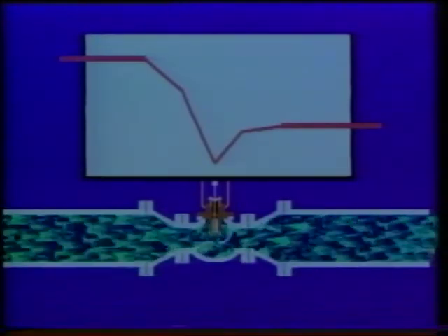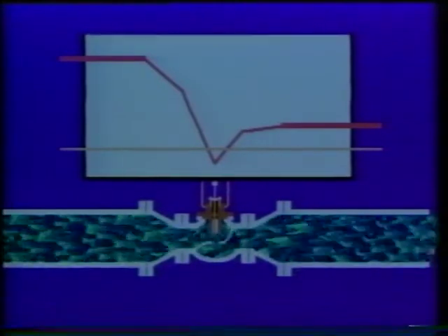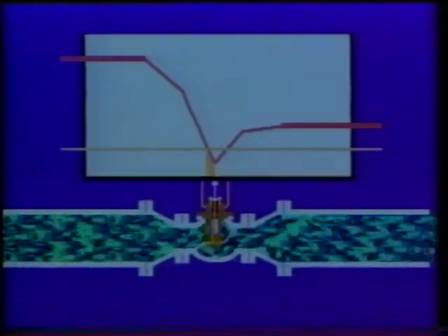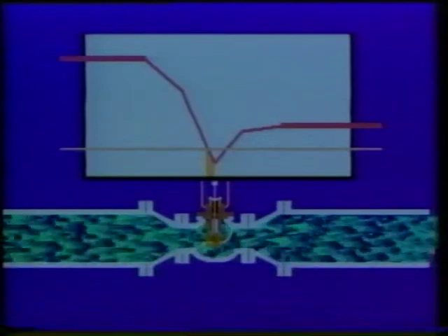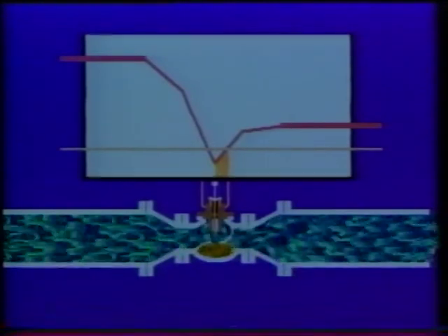Now consider the instance where the vapor pressure of the process liquid corresponds to this line. Process liquid below this pressure is below its boiling point. With the proper conditions, vapor bubbles will form in this region. Then, after passing through the vena contracta, pressure recovery in the valve will cause the vapor bubbles to condense and collapse. As you may be aware, the implosion of these vapor bubbles results in noise and can cause extreme damage to the valve. Also, cavitation can reduce the capacity of the valve.